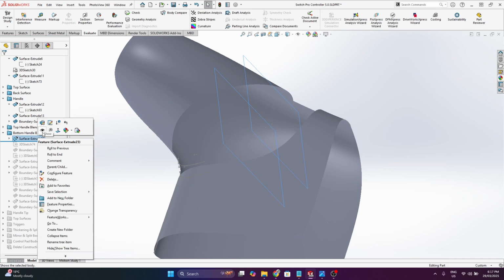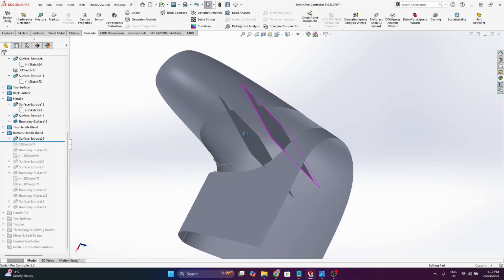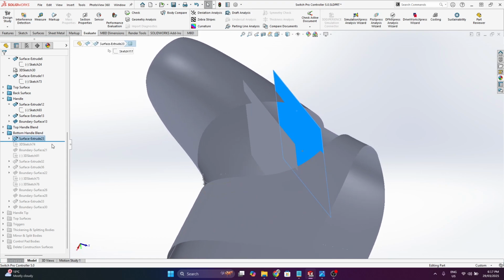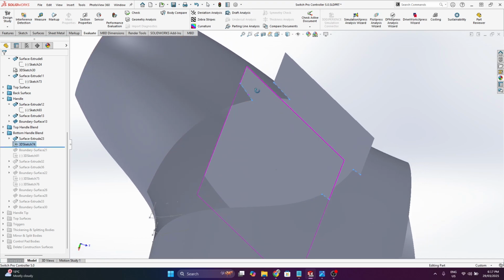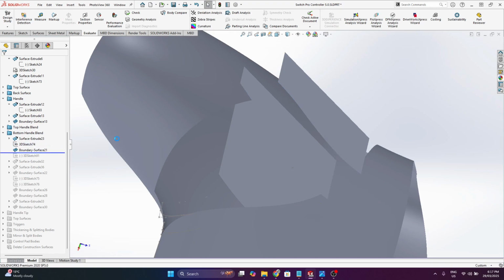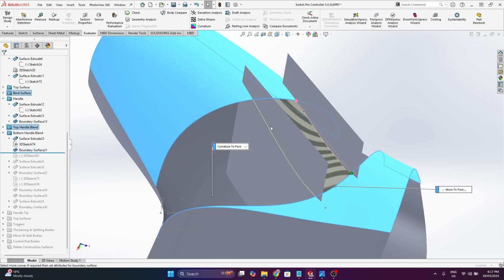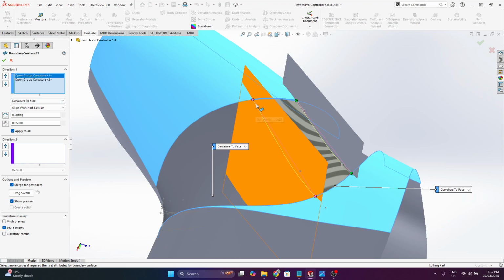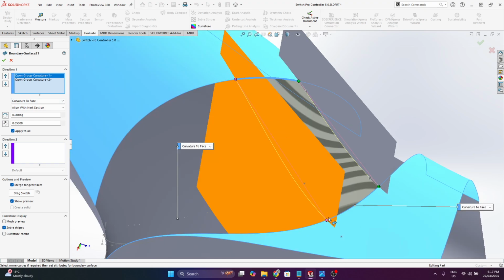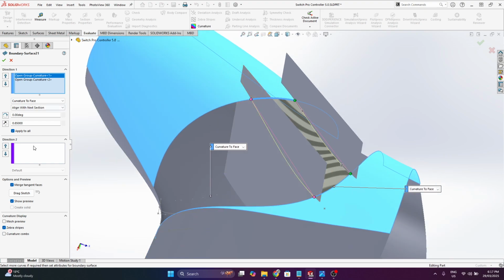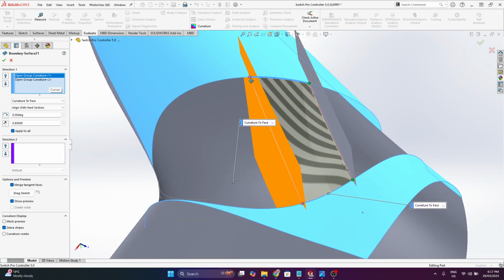So actually, in this case, yeah, I did draw some flat planes, and I think my intention was to make some intersection curves on them and then use them to build a boundary surface. But I didn't even actually use them in the end. So I just left these edges floating in the second direction, and just used edges in the first direction, terminated by either 3D sketch points or some reference feature or reference sketch.